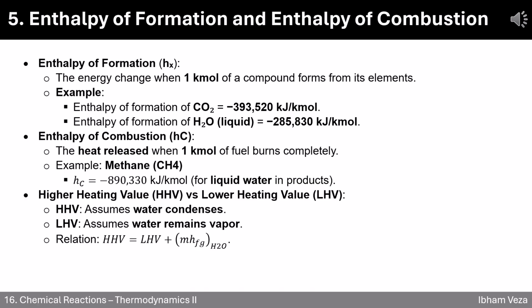For example, when CO2 forms, it releases negative 393,520 kilojoules per kilomole. Next is enthalpy of combustion. This is the heat released when 1 kilomole of fuel burns completely. Take methane, CH4, for instance. It releases negative 890,330 kilojoules per kilomole when burned to form CO2 and liquid water.